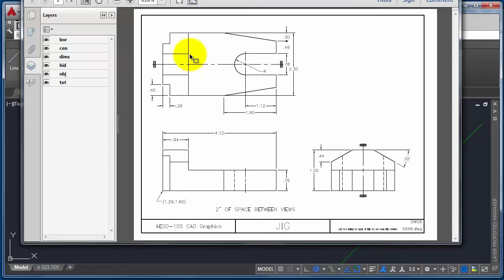Now, the edges that are here may look like they're the same width as the edges of my slot. They're not. These come from a different position entirely: the top surface of that right side view, where the resulting line segment is determined by this linear dimension in this angle. Don't assume that you can just track lines across. This is not correct. In this position, we'll need to use the miter line to fill that information in. We don't have this done yet in our right side view, so we'll wait until that's finished to enter those edges. We move over to the right side view now.